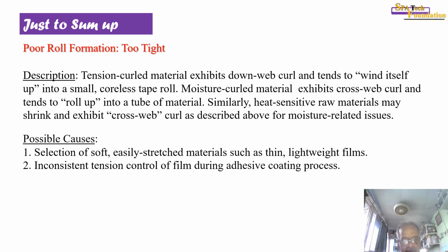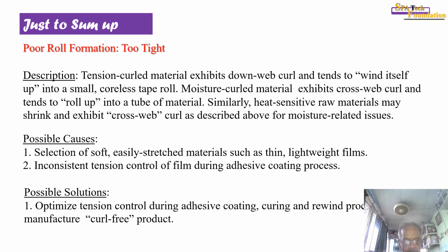Possible causes: selection of soft, easily stretched material such as thin, lightweight films, inconsistent tension control of film during adhesive coating process. Possible solutions: optimize tension control during adhesive coating, curing, and rewind process to manufacture curl-free products.